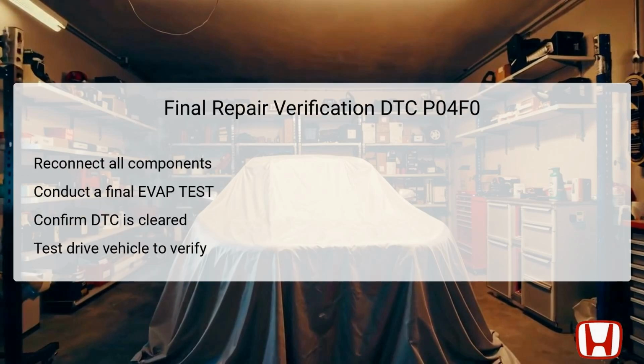Once all troubleshooting steps have been executed and any necessary repairs made, it is crucial to perform a thorough final repair verification. Begin by ensuring all components and connections are properly reassembled and secure to prevent future malfunctions. Next, conduct a final EVAP test using the HDS to confirm that the system is operating correctly without triggering the DTC P04F0.